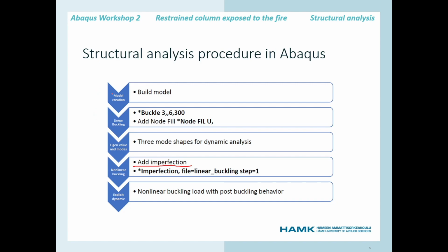First we create the model for the structural analysis, and then we separately perform the linear buckling analysis, and then we write the node file command at the end of the output request, and then we obtain the desired mode shapes, the buckling shapes, for the dynamic analysis.